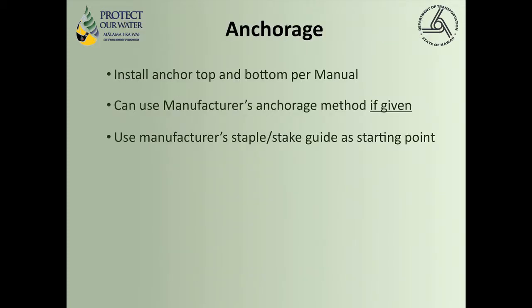Anchorage. When I look at anchorage, I look for anchorage installed per manual. You can use the manufacturer's installation instructions if they are given for your product. The manufacturer's staple and staking guidance and the BMP guidance are starting points. That doesn't mean if you count up and it was every 3 feet and you count up precisely how many stakes, that's all you need for it. You need to have complete contact with the ground.